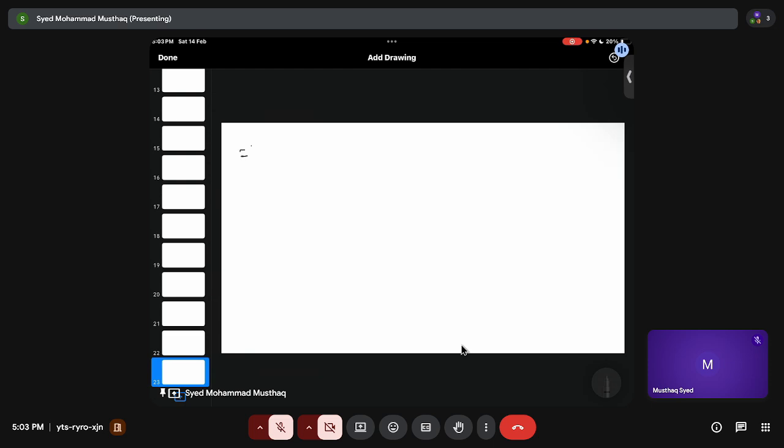So how to do the heat balance, from where is the heat coming? Heat is coming from the sensible heat, I mean the heat that is being carried by the reactants. Sensible heat from reactants, what are the reactants? Air plus fuel, plus whenever this air and fuel react, it will give heat, and that heat is coming from combustion. So heat coming from combustion.